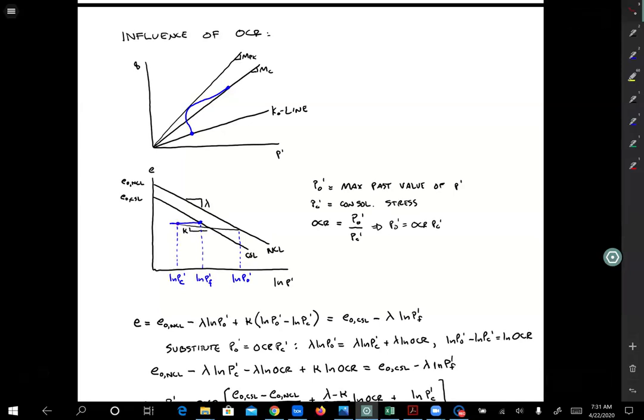Now this is dense of critical state, right? We've moved to the left of the critical state line. We know that the stress path is going to be initially a little bit contractive before becoming dilative and reaching failure on the critical state line. So if we come up here, this is our stress path. And notice that I haven't drawn these lining up anymore, right? If you were to draw a vertical line up here, it wouldn't match. This one is kind of close, but not really.